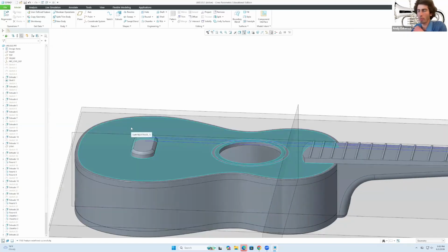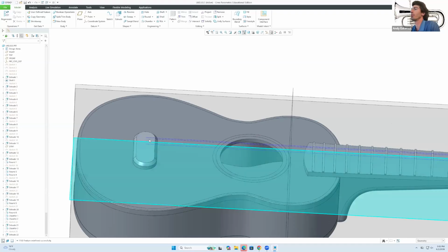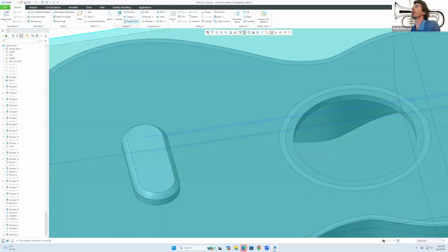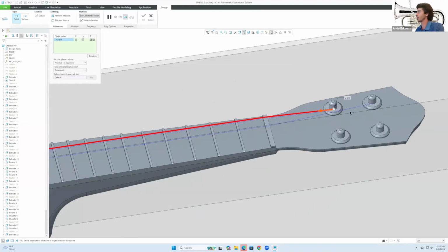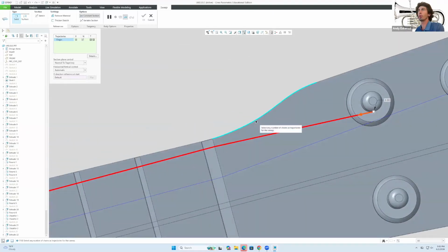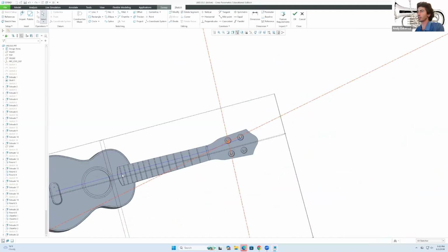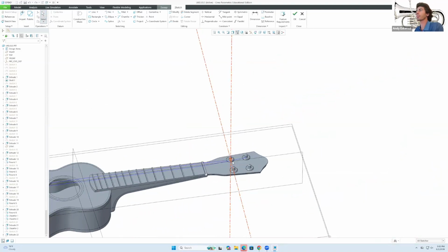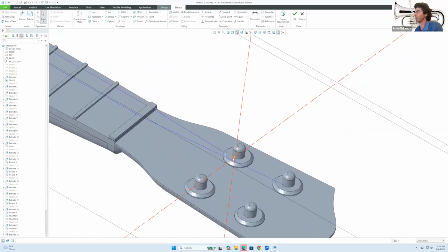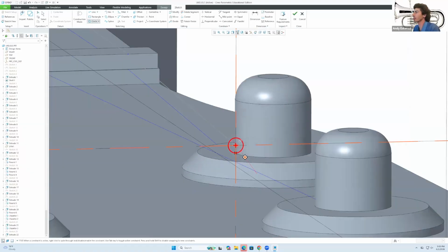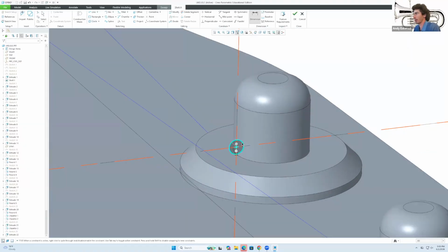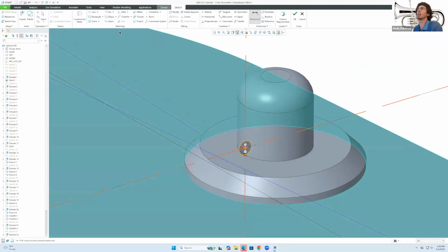So we have most of what we need right now. So what we're gonna do is the following thing. I'm gonna go here to say sweep, and it's gonna first prompt me to select this chain, which you can see going all the way like that. And then when it comes to sketch, I think, yeah, that should be fine. What it detected is here, using the normal, I'm just gonna draw a little circle that goes like that. And we provide that data. Oh, actually, it recognizes it's 0.5, but that was anyways what I wanted to do.